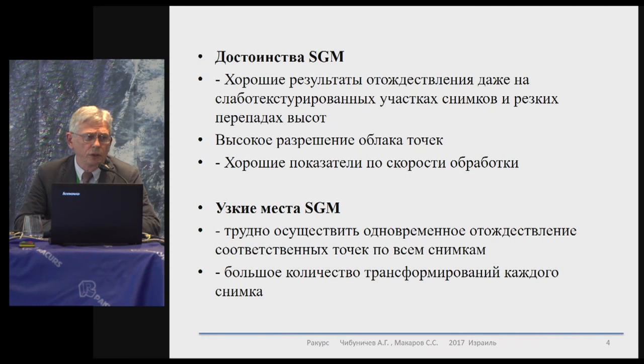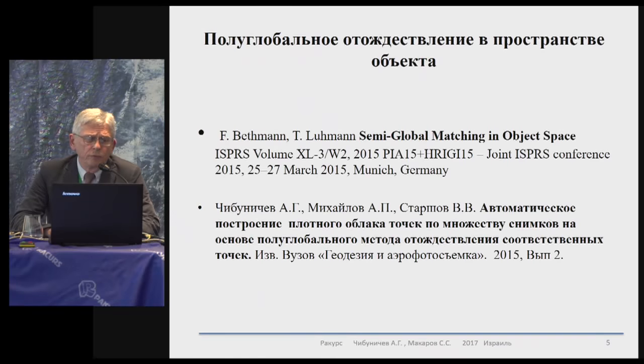And if we take aerial imagery acquired from UAVs, the overlaps are multiple there, and each time we have to transform them. We can transform each image a dozen times. Sometimes it could be so difficult and so complicated. That is why naturally it slows down the process considerably to build a dense point cloud, and we need to somehow combat it. Most importantly, we're not using to the full extent all photogrammetric connections in this regard.